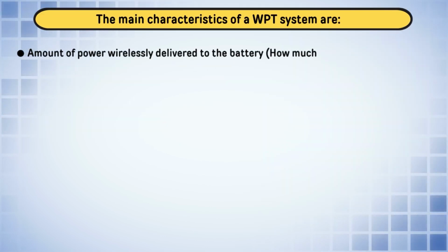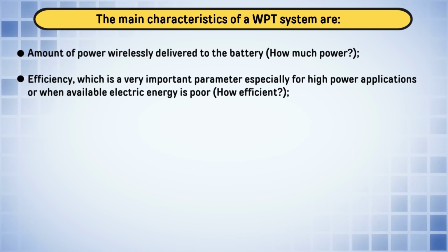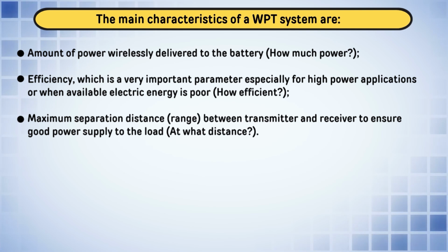Another topology is the forward converter, and it provides very high efficiency for medium power applications. We have the full bridge converter, used in high power EV charging stations, as this converter is able to provide isolation. So, it is safety critical, useful in onboard charger and interconnection systems.